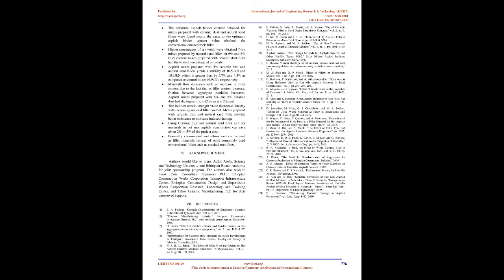The weight of compacted specimen increases with an increase in asphalt binder content, because asphalt binder fills out the air voids and lubricates the aggregates' movement, which allows for denser compaction. The optimum asphalt binder content decreases as filler content increases, due to the fact that the void space between aggregates is filled by filler materials, so there will be small room for asphalt binder to occupy.